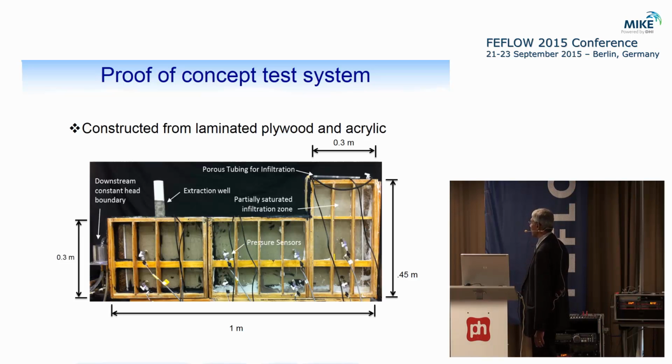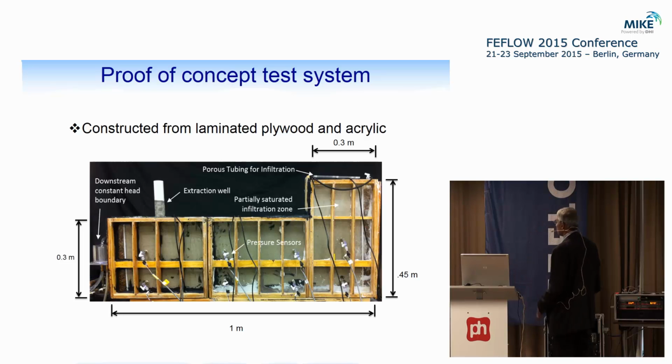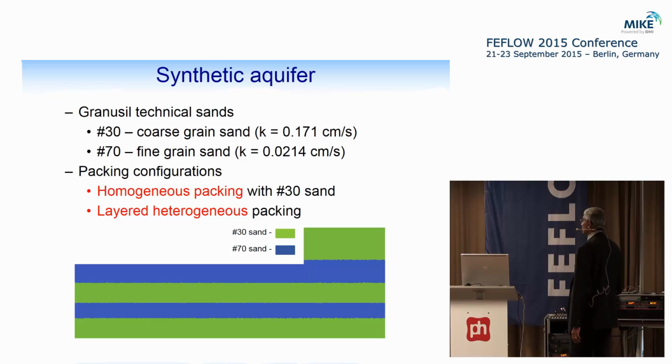What you see here is a tank with an L shape. This is the unsaturated zone. There's a recharge system here, simulating the recharge, and then there's a well pumping the water here. There are a whole bunch of different sensors. There is the soil moisture sensor, but in this particular case, we don't have soil moisture. In the next one, we have pressure sensors, temperature sensors, and water quality sensors. We are putting a bromide solution into this one, and the sensors give the real-time data. The whole idea is to see whether we can develop an algorithm to control this and take the water out here. This is some of the early experiment we did.